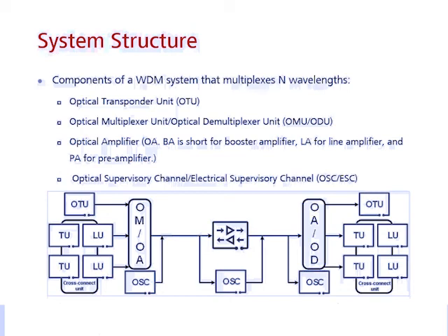Before we send out, we still have the last step, that is OSC. OSC means optical supervisory channel, like our protocol channel in the flash, you see. So during the transmission, we need some supervisory channel that can monitor our service status and transmit some command signals or overhead signals between two stations.